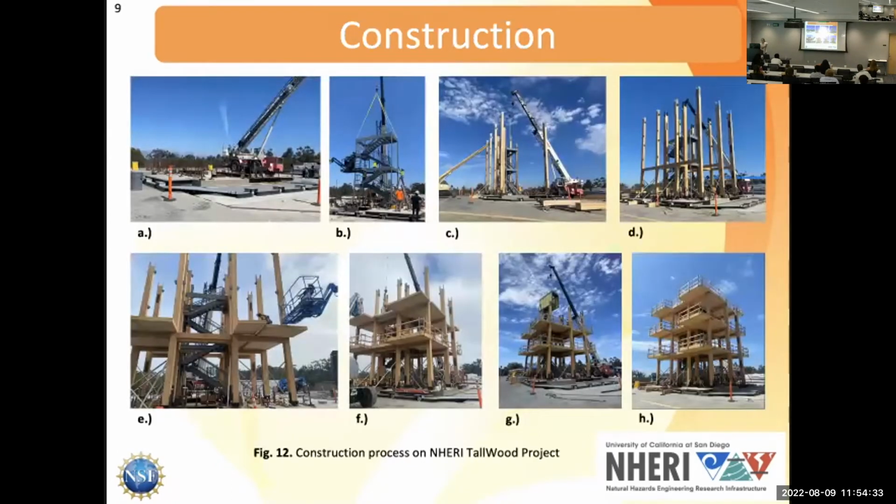So the next theme is construction. Once all these structural pieces are fabricated, you can put them up pretty easily. What's unique about the construction for this project is it's called balloon type construction. So basically you have all these continuous members that everything else gets attached to, and you just keep building and building until you get to the height you want. I'll explain the process so far. You start with the foundation seen in A, and then for this project, we put the modular stairs in place because the building gets built around these stairs since they're a non-structural aspect.